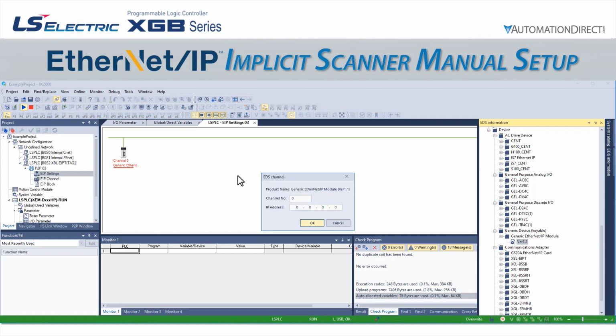Doing this opens the EDS channel pop-up window, and here we can set the channel number and IP address of the drive we are connecting to. In our case, the drive resides at 192.168.27.105. The channel number is used by the software to determine which device we are targeting when we set up our communication blocks in the next step. The system will automatically increment the channel number for each additional device added, and it will not allow duplicate channel numbering. We will leave this at 0.